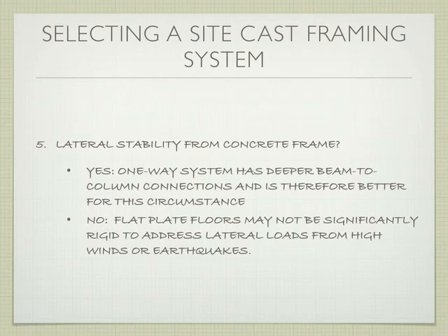So the other thing about concrete that's important to recognize is that if you're ever doing retrofit work on concrete, it can be very, very challenging. So you have to plan ahead in concrete if you want anything to be run through the concrete. If we're going to put electrical in, if we're going to put plumbing in, all that stuff has to be planned ahead, because you can't go cutting into a slab.